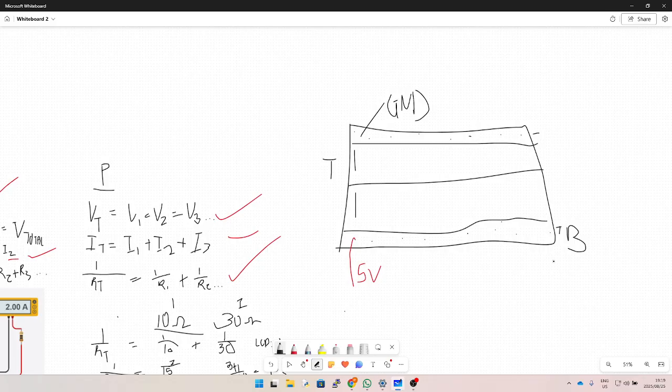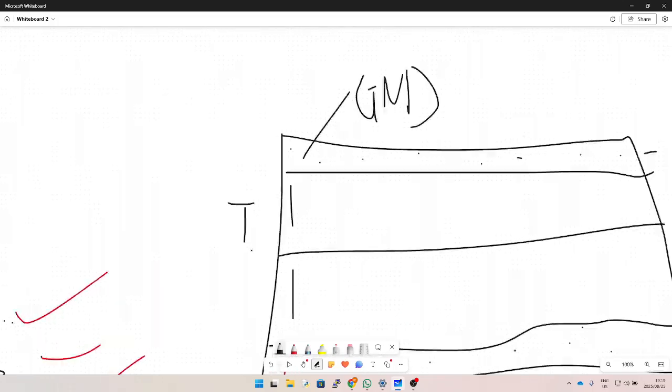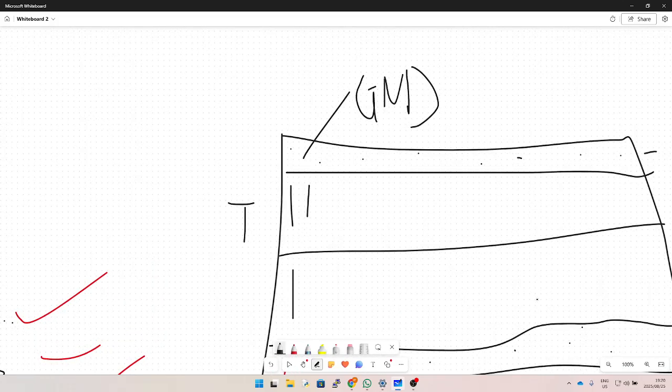So the bus strips are your power source, meaning you're connecting a 5-volt and a ground to it. Your terminal strips are where you place the actual components. For example, as I said yesterday, there's two ways.